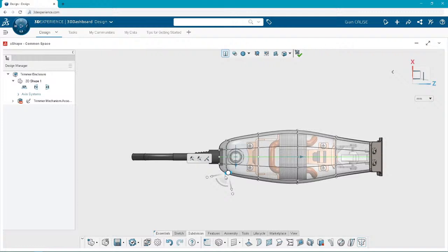If you select a single point, it's going to give you arrows that point directly normal to the surface, and then in the lateral and transverse directions, which is what you're seeing right now. But maybe I need to move it only in the X, Y, or Z direction. Well, you can toggle that on just by right-clicking on the robot, and now it will keep you in that mode, only moving in the X, Y, or Z direction until you change it.